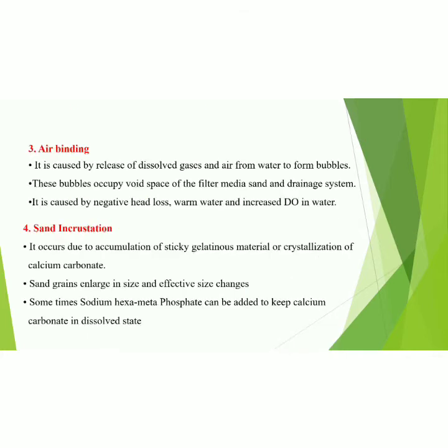Next, air binding. It is caused by release of dissolved gases and air from water to form bubbles. These bubbles occupy wide space of the filter media, sand and drain system. It is caused by negative head loss, warm water and increased DO in water. So those bubbles will come and accumulate in the pore spaces. Again, they will reduce filtration rate.